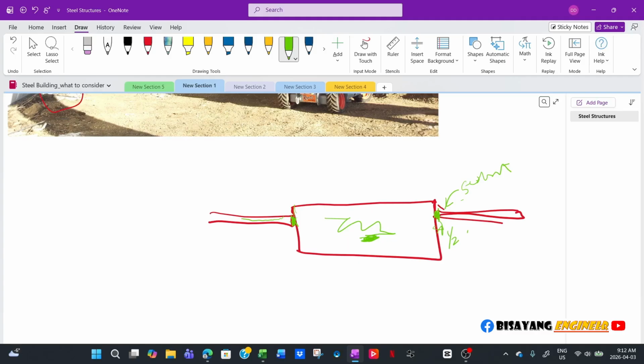And then the reason why this is big is because you need a heavier foundation to dampen the vibration. So imagine if you have an equipment sitting on, say, a 4 inch slab versus a 30 inch slab. The 4 inch slab will vibrate more compared to a heavier foundation.